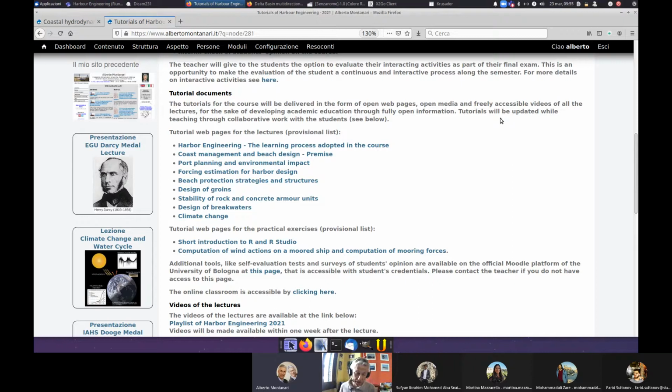And the distortion is basically related to the more relevant role played by the viscosity of water in a small-scale setting. You understand that you cannot reproduce, for instance, turbulence in a glass of water, because in a glass of water it's extremely difficult to develop turbulence because the viscosity is playing a relevant role. Turbulence usually takes place in large spaces.